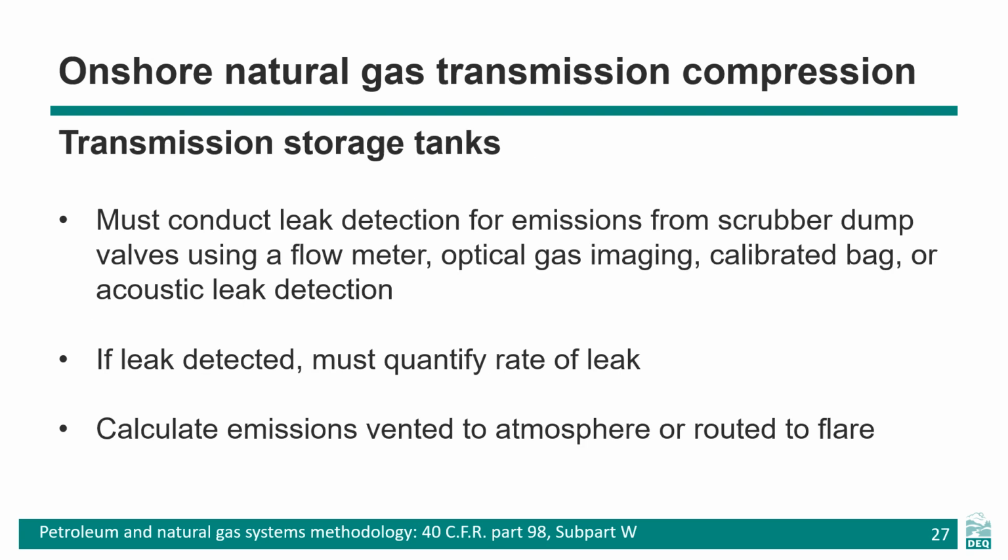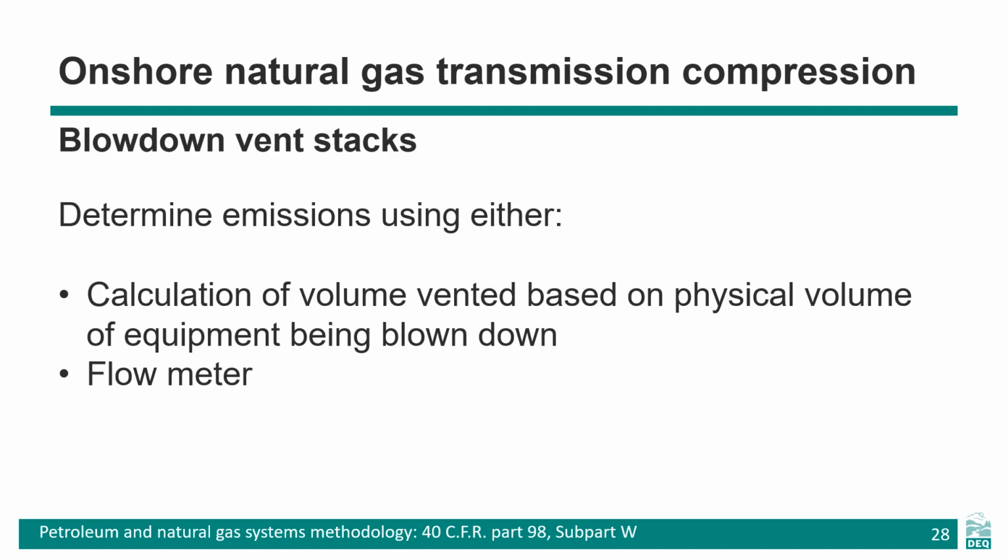Let's move on to transmission storage tank emissions. Emissions from scrubber dump valve leakage must be monitored annually for leaks. If a leak is detected, the rate of emissions must be measured with a flow meter, optical gas imaging, calibrated bag, or an acoustic leak detection device, and the emissions from the leak over the year must be calculated. Emissions must be calculated for venting to atmosphere or from flare emissions if routed to a flare.